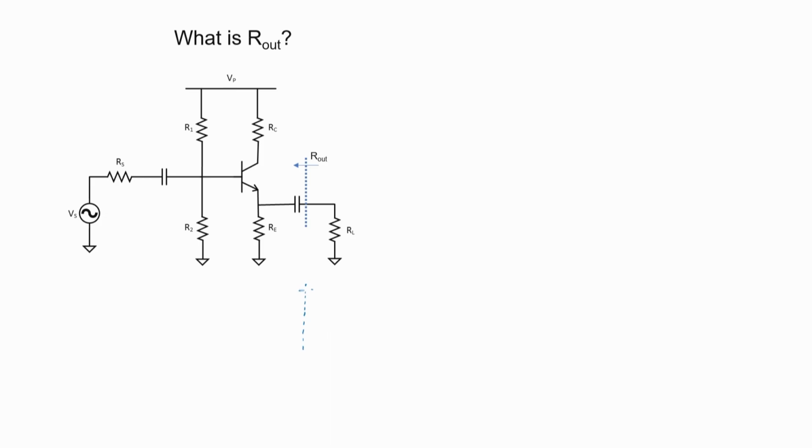Looking to the left from the perspective of a small signal, I see my emitter resistance R sub E. I then have my little r sub e, and then I have to imagine that we have a wall, and anything on the other side of the wall can be reflected to my side of the wall only by dividing by beta. R2 is attached to ground. R1 is attached to an AC ground. For small signals, that capacitor doesn't exist.